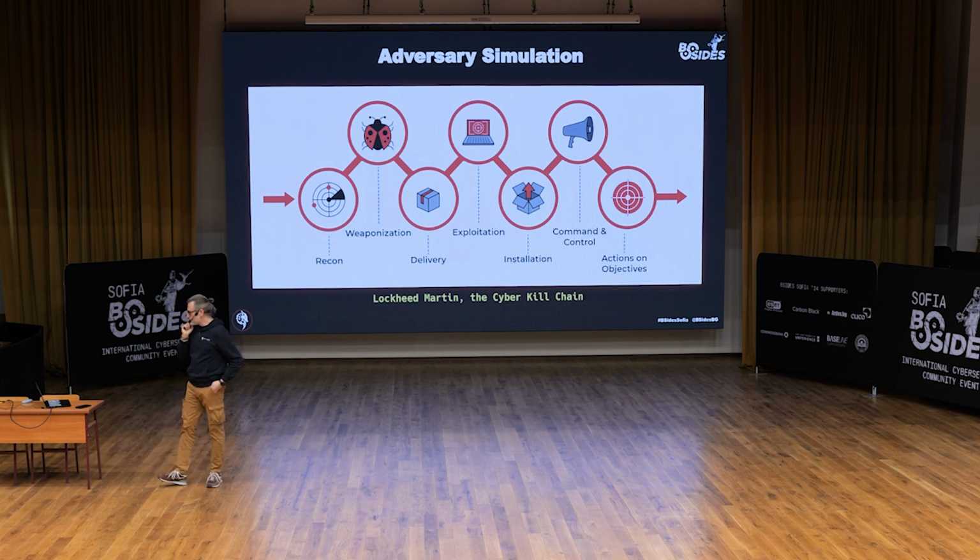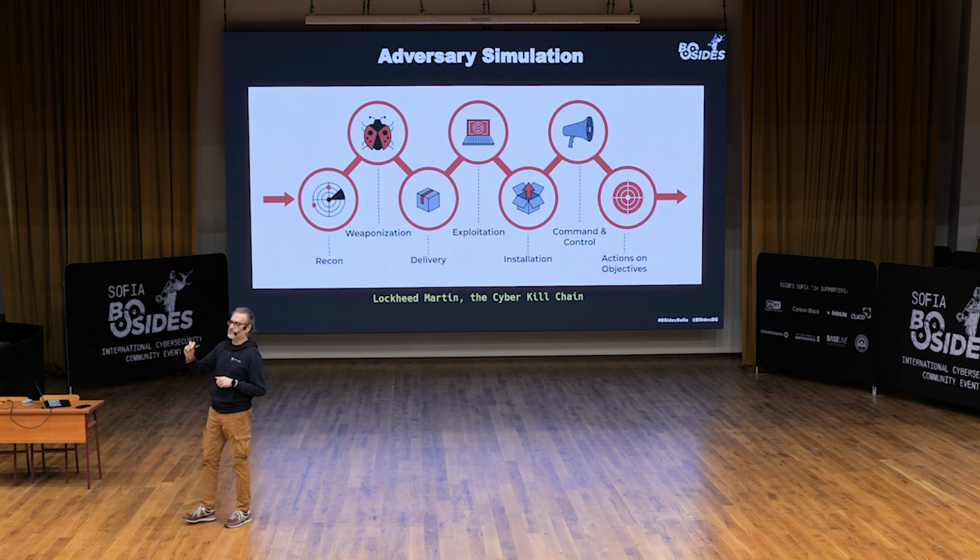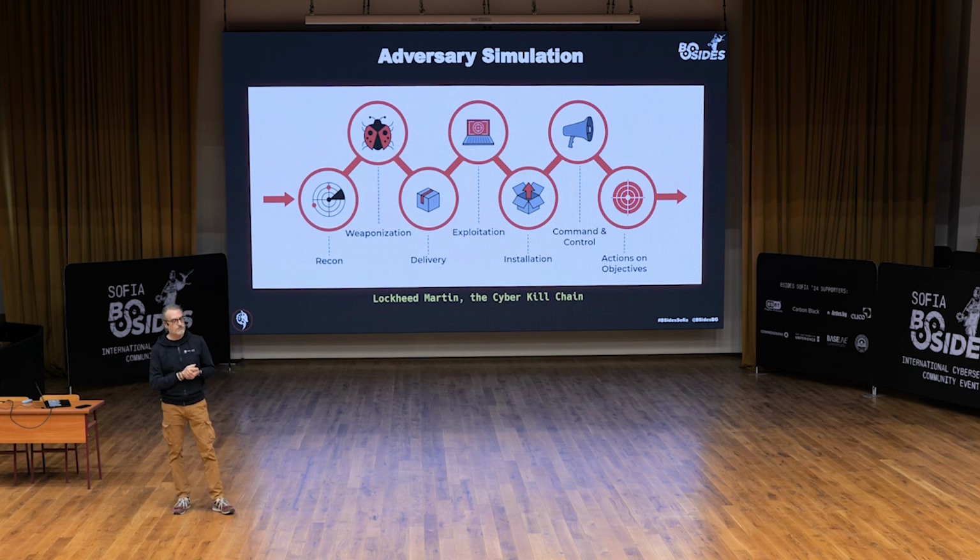The first point is why we talk about adversary simulation. In the OT domain, you can find a list of tools, not so long, but okay, that can be useful to identify vulnerabilities. Tenable OT, this is the Nessus version for the OT domain. You can find Claroty, Nozomi Guardian, Radiflow, Armis, which are typical tools that scan the network, grab information from the PLC, and tell you, okay, this version of the firmware of the PLC is potentially vulnerable to this kind of CVE and so on.